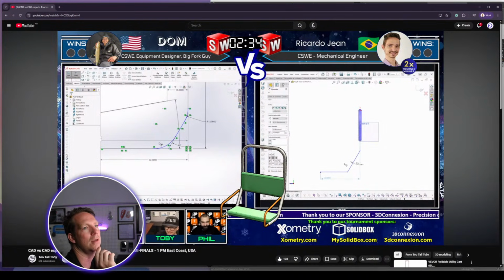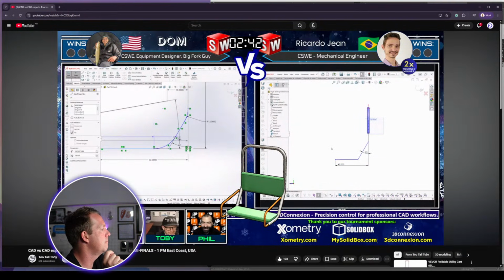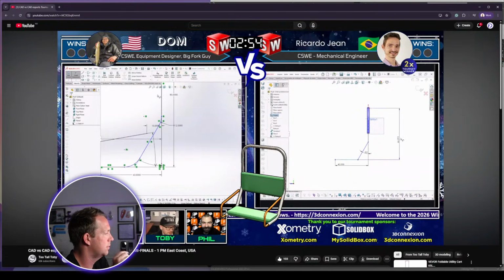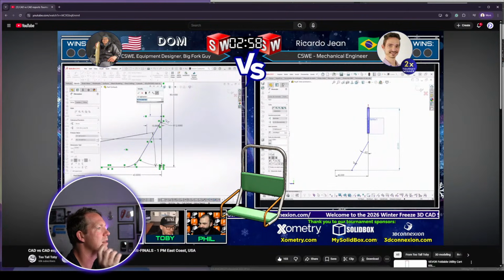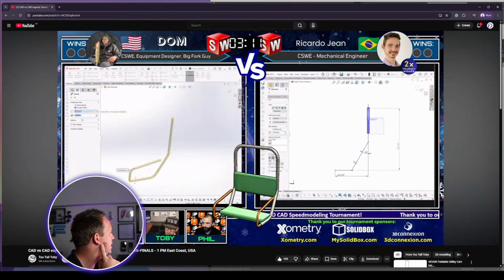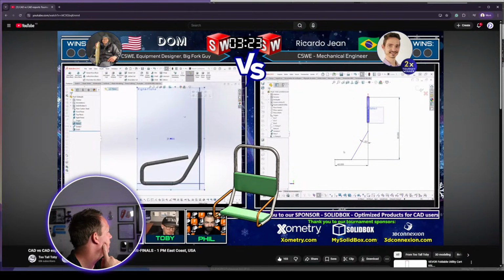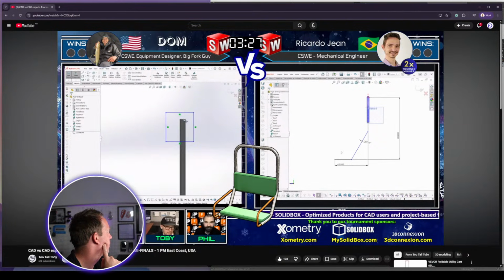Like we know in SolidWorks, there's multiple ways to do everything, but with a 3D profile like this, it's probably 3, 4, 5 different ways that you can do that. Which one's going to be quicker? I'd say I did extruded body so I can make 3D sketch for the tubes, then the bench and rest, then indent for fun, and delete bodies clean up.